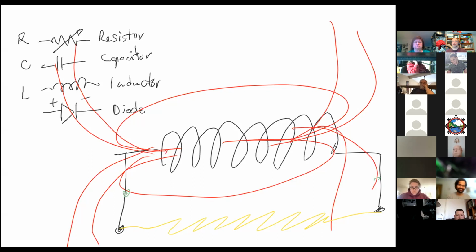So is that how you get a radio spark for transmission? That is how a spark gap transmitter used to be made a long time ago. Now, the thing is that a spark generates radio frequency energy on a lot of different frequencies. It's very broadbanded. So what you would do is put this through a filter, and you would try to generate just the frequency that you intended.